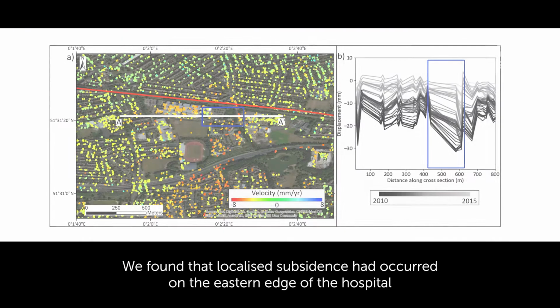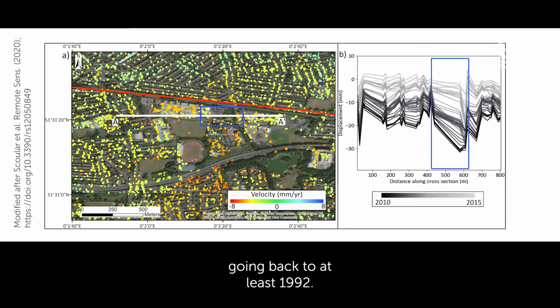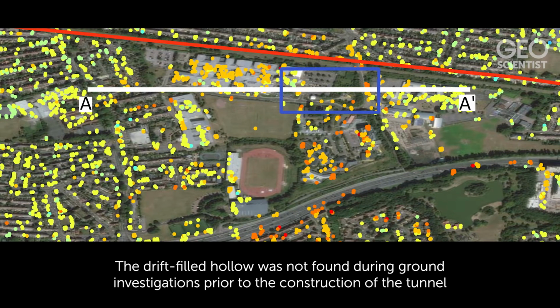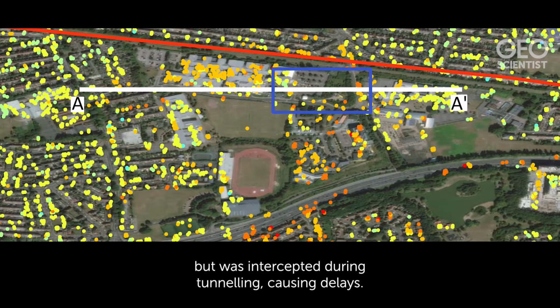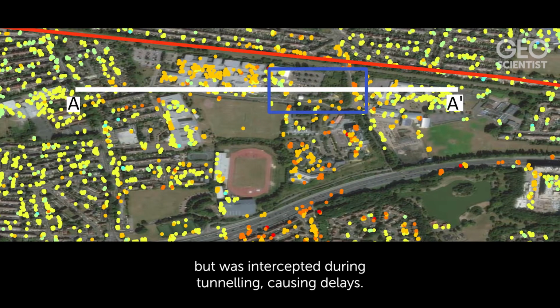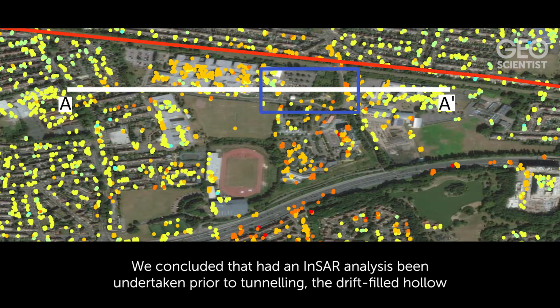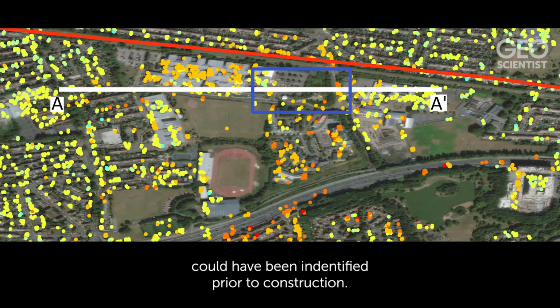We found that localised subsidence had occurred on the eastern edge of the hospital going back to at least 1992. The drift-filled hollow was not found during ground investigations prior to the construction of the tunnel, but was intersected during tunnelling, causing delays. We concluded that had an InSAR analysis been undertaken prior to tunnelling, the drift-filled hollow could have been identified prior to construction.